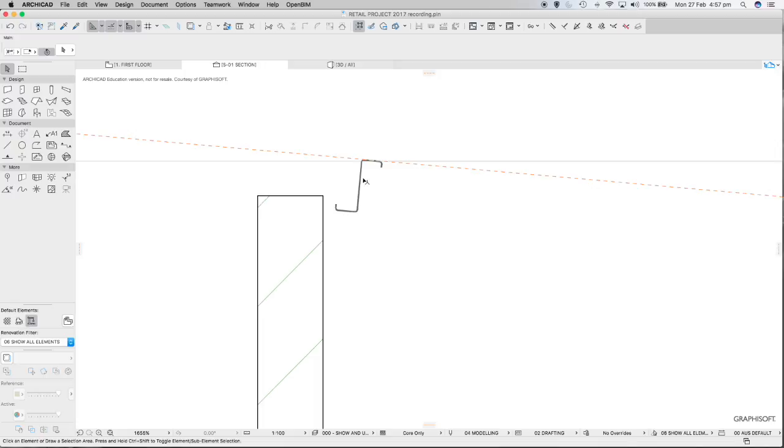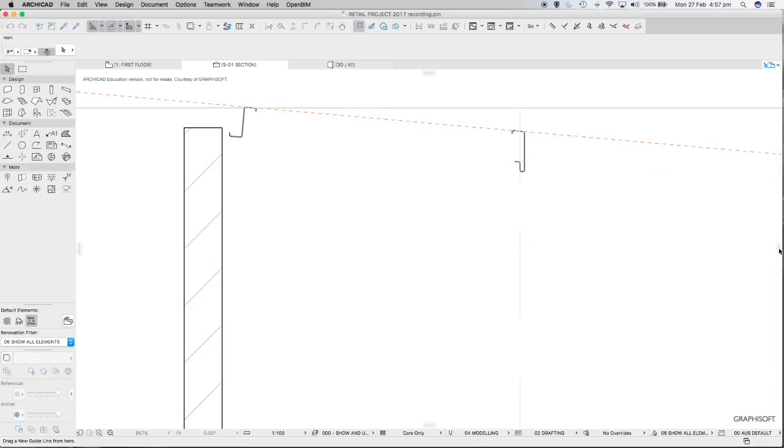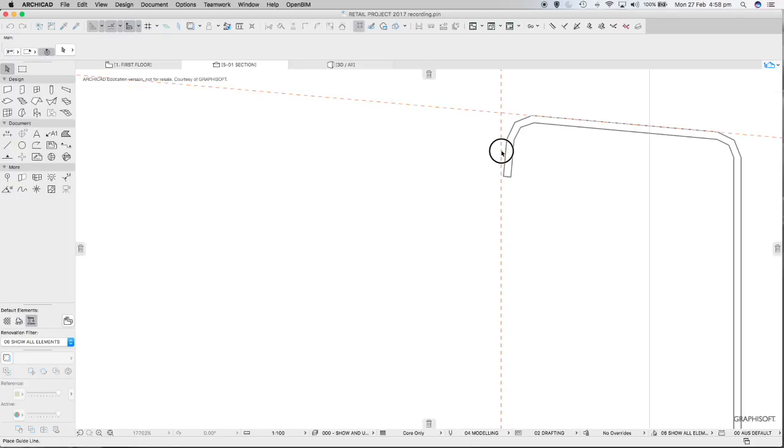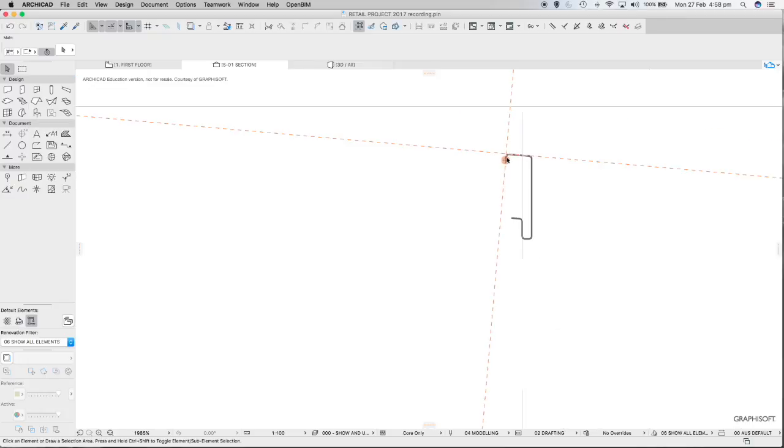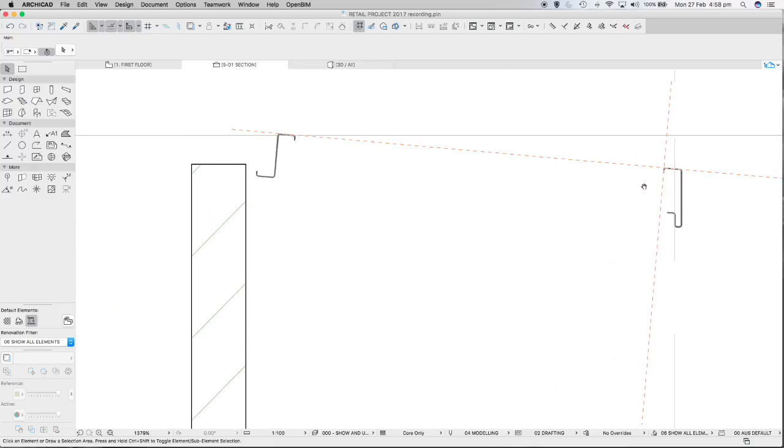Okay, so now we've got the Z purlin. If you can imagine, sets of cleats would normally come on this back face here like that. Now, if I want to establish the spacing of that first purlin, probably what I would do is grab a grid line and zoom in here to this edge of this first one and place that there. That would be similar to the left-hand side of this web member, to find the position of the next one.